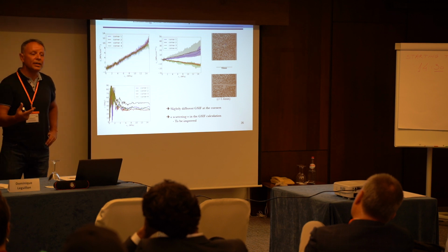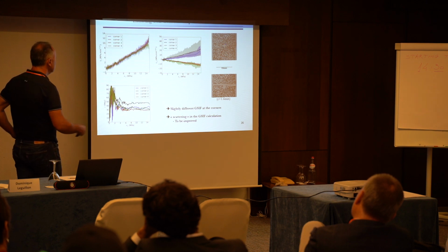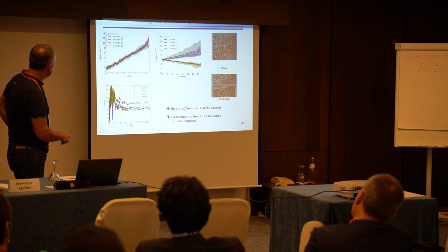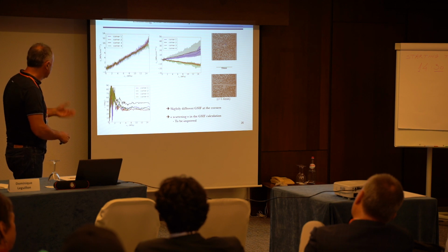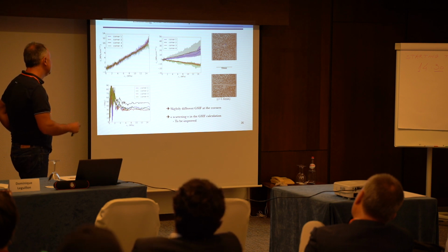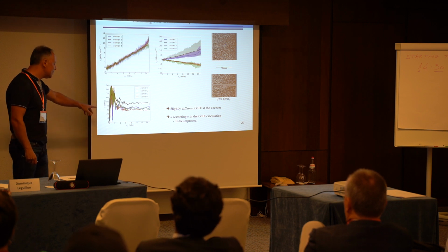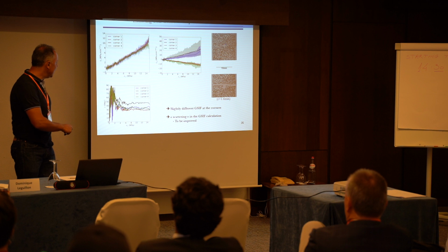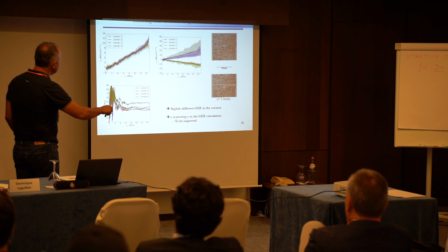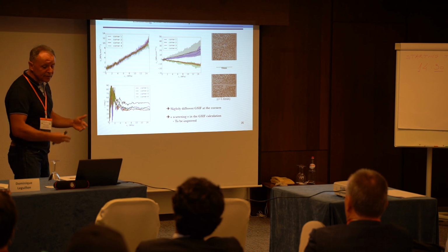So how can we improve this? By improving the speckle, first. And second, by transforming this line integral into a surface integral. Still, for mode 1, it is reasonably, we think, acceptable as it goes here. For mode 2, it is slightly different. And for the mode mixity, it is really somehow a little bit questionable, at least at the beginning. So with this, we do what? If this corresponds to the onset of crack propagation, we can estimate the critical generalized stress intensity factor and work on that.